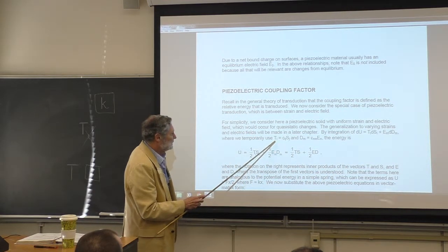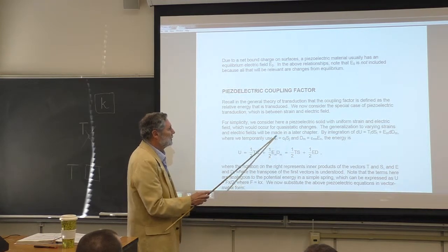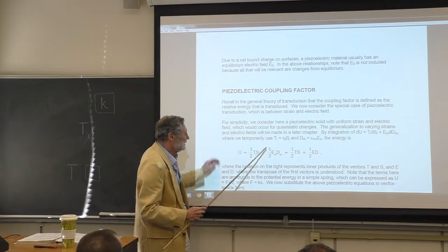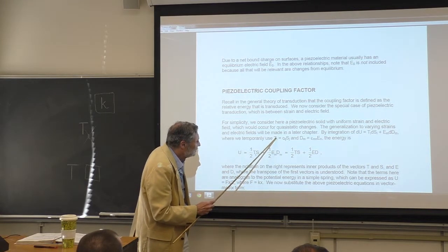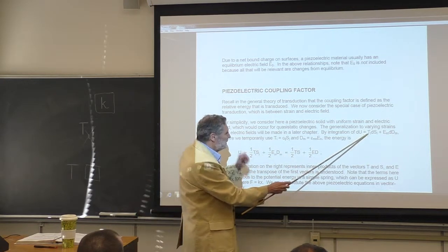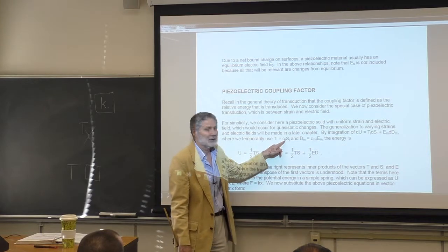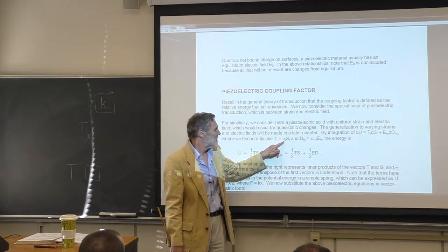We know the dependence is given by the Hooke's law stress-strain relationships. So I want you to imagine, I need to edit this a little bit, but it's simple: substitute this expression into here, and then integrate with respect to S. We're of course assuming these are constants. The stiffness coefficient, are you starting to see it?